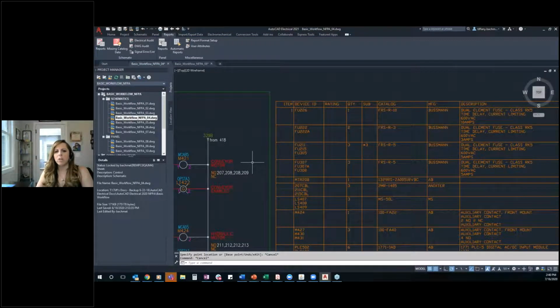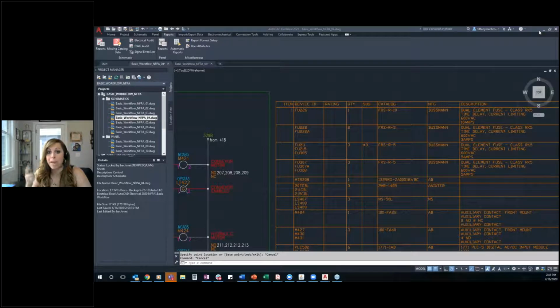So there are lots of ways to do that, but I would want to explore more how you might approach it from being able to get the data right in your drawing as opposed to manual overrides. Just a piece of advice there so that you don't have to do all that manual work. I try to get people doing the least amount of manual effort with electrical as they possibly can. It's typically the goal. Whenever I find people having to manually type anything, manually hide an attribute, add one, doing a lot of really manual efforts, to me, that means something's not set up right.